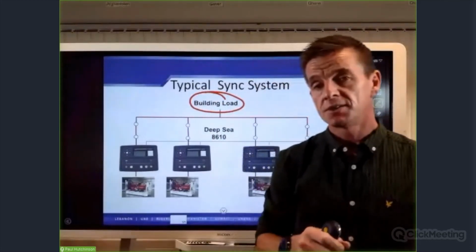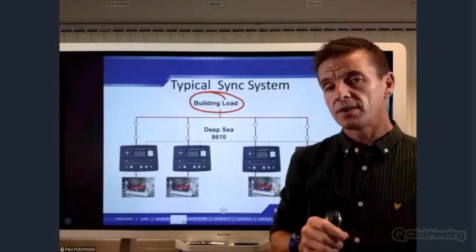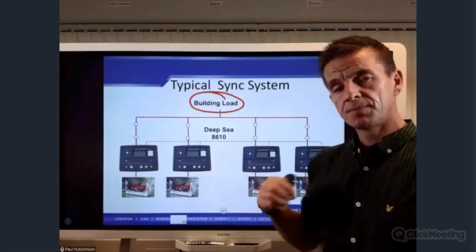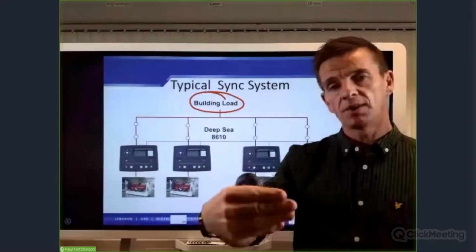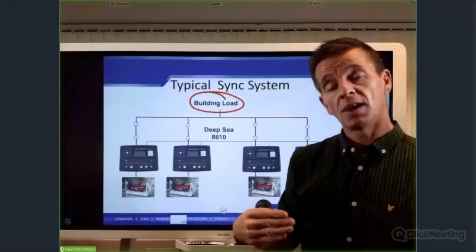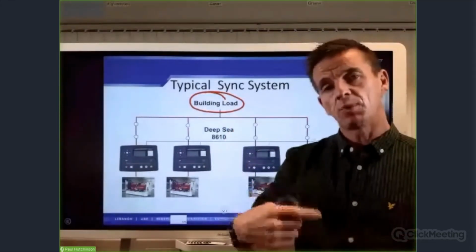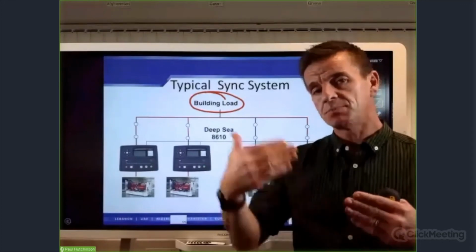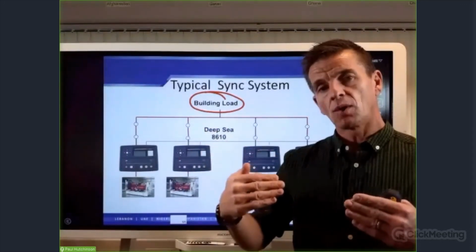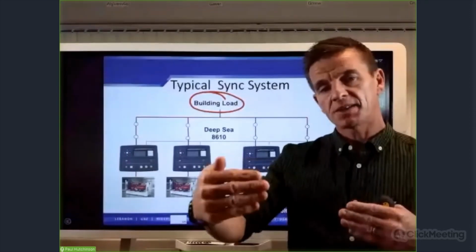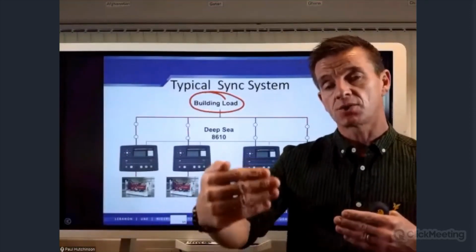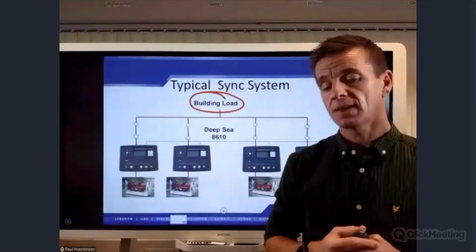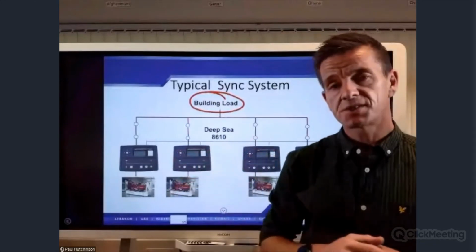As we said earlier, depending on where the load levels are and how we've configured our network priorities, gensets will be synchronized on and offline according to the programming set points that we have programmed inside the controller. This ensures that we have plenty of capacity left in the system if we start to take units off, or enough capacity to bring other gensets online quickly as load levels start to rise. So that's how that system works.